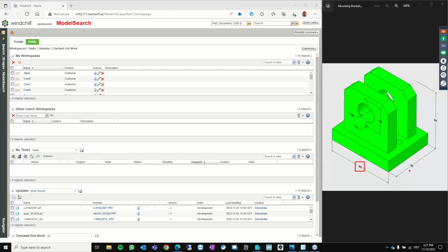In my case, I do know the main dimensions, like I know the model has a length of around about 90, a width of around about 70, and a height of around about 87. I also know some additional attributes, like there is a hole diameter of 25, because I need to stick a bolt through that hole. And I also know that I have 2 drillings with a diameter of 5, and they have a hole pattern distance of 40. I know those dimensions because I have to screw a plate with those holes on the mounting bracket.